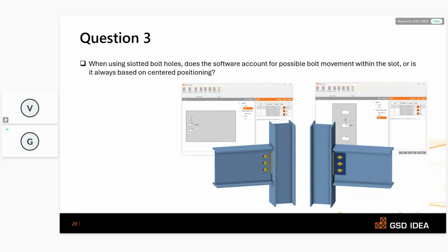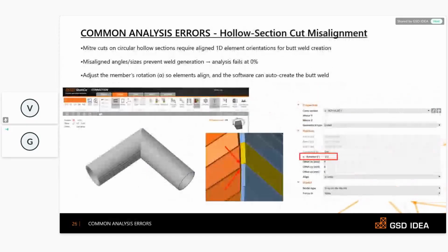I would also suggest you to check one more thing. Check the member orientation. Just like how we corrected the alpha rotation value in here, certain models, when we import it from any third party software, the alpha beta gamma values might have a slight change. It might not be always zero. It could be plus or minus 1.1 or 2 mms tilted, which gives no space for the butt weld, especially when you're butt welding. And at that time also the singularity might happen.